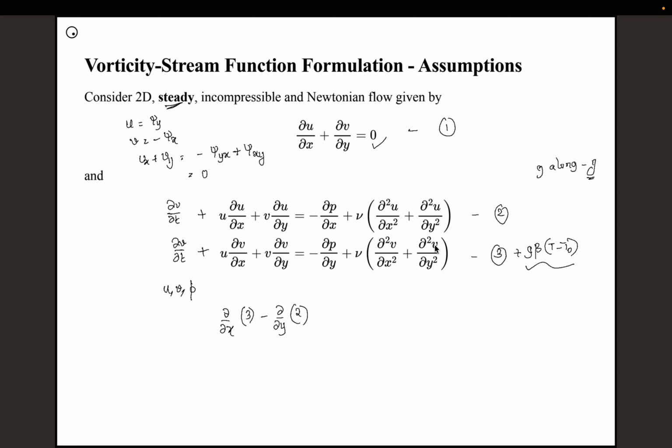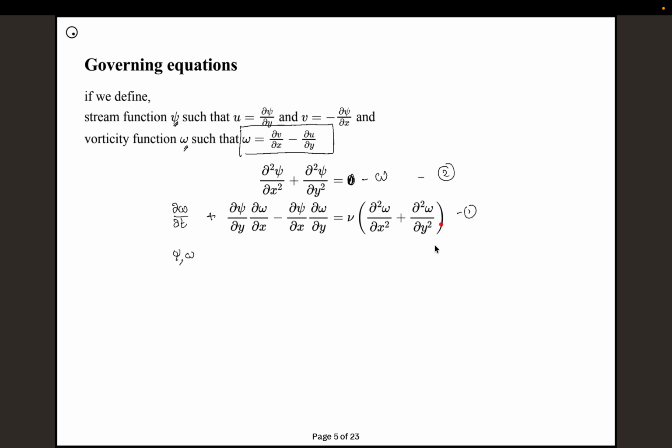The additional source terms. So when you do the derivative, these source terms will also get converted accordingly, and you'll have some additional terms in this original omega equation itself. So you'll have some source terms. I'll just denote this as S. So if you want to write a general solver, all we have is a vorticity transport equation. This is a vorticity transport equation.